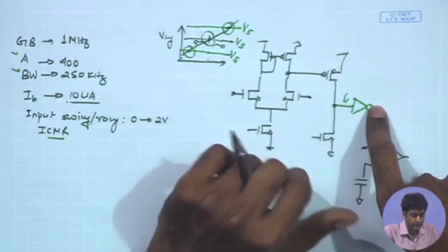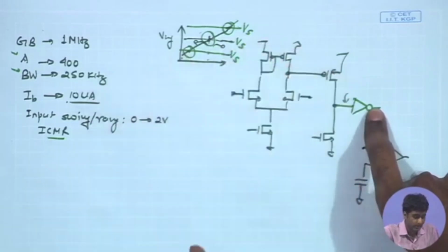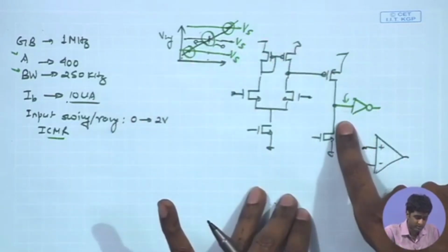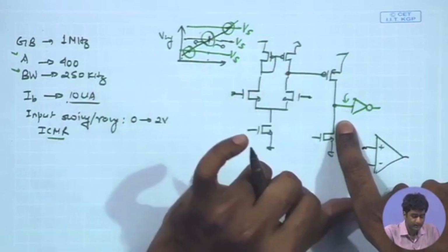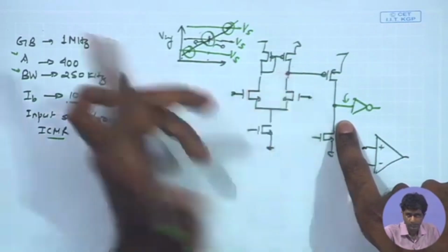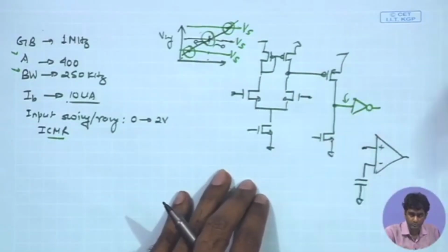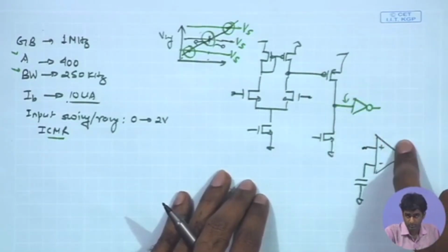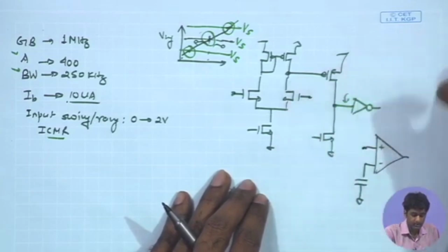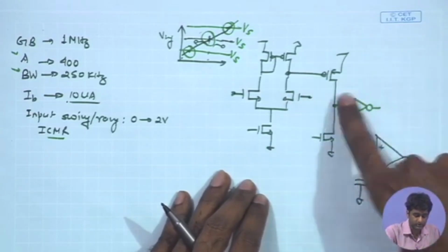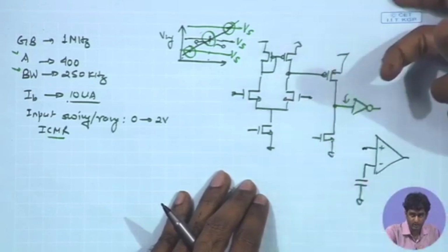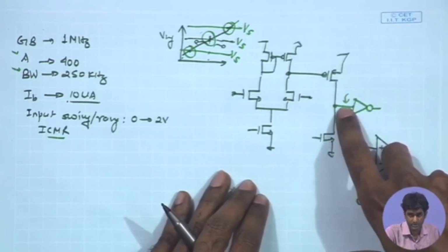Therefore, what we can say is in the overall case, if you are not having any significant load capacitance over here, in that case the pole over here can become the dominant one. Of course, it depends upon the condition. Means if your comparator output is feeding a lot of other logic gates, and you are having a lot of other digital circuitry being driven by this output, then it can become a dominant node. You can have a large capacitance over here.